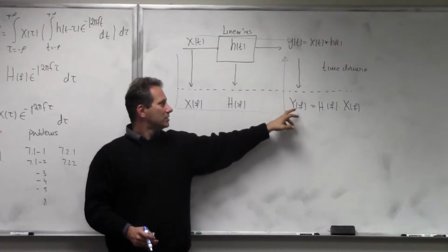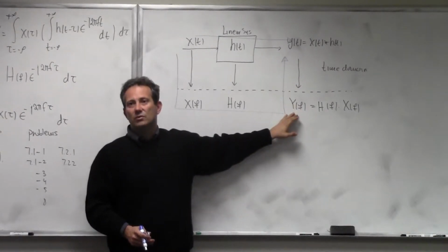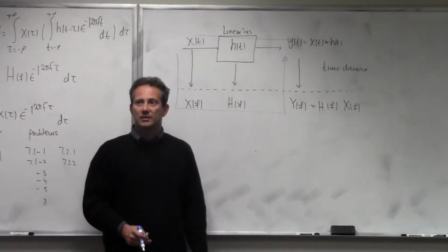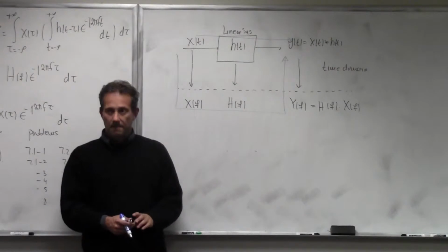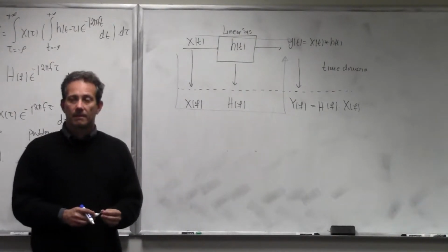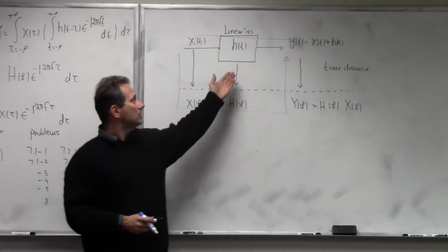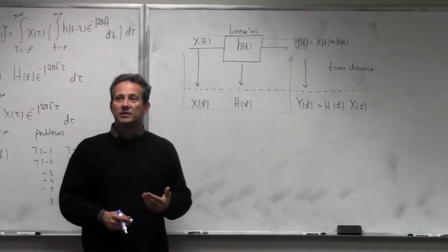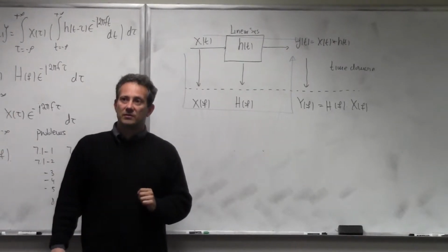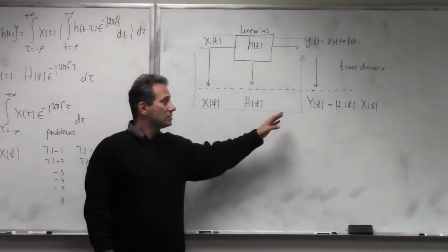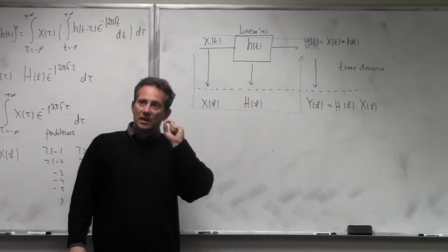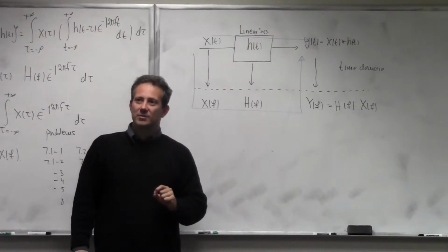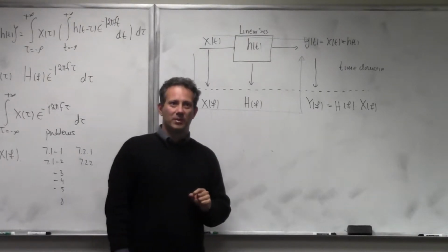A lot of times we can actually stay here and conclude whatever we need to conclude just by looking at the frequency response or the Fourier transform of the output signal. Right? So are we doing any significant change of the sinusoidal signals in the output? Yeah, depends what this filter is. This filter may kill some sinusoids. Let's say if it's a low-pass filter, it can kill all the sinusoids that are above a certain cutoff frequency. So it can change the spectrum. The point here is it cannot bring new sinusoids, right? Some of them may disappear, but no new ones can appear.